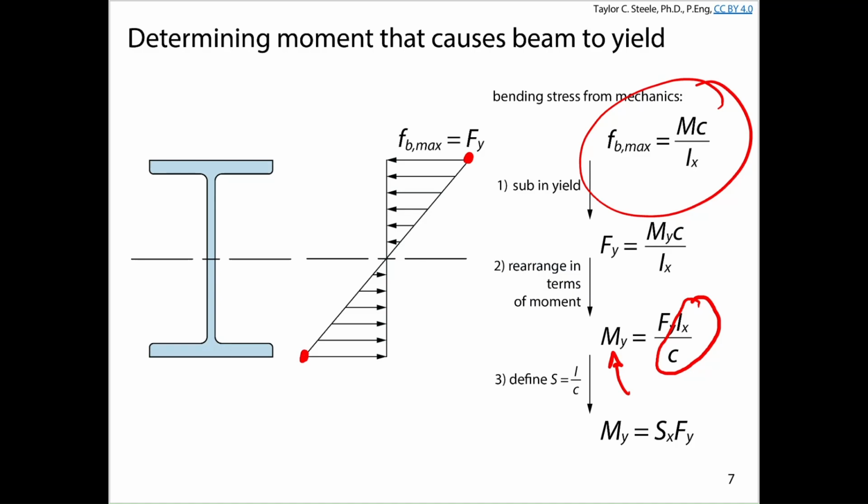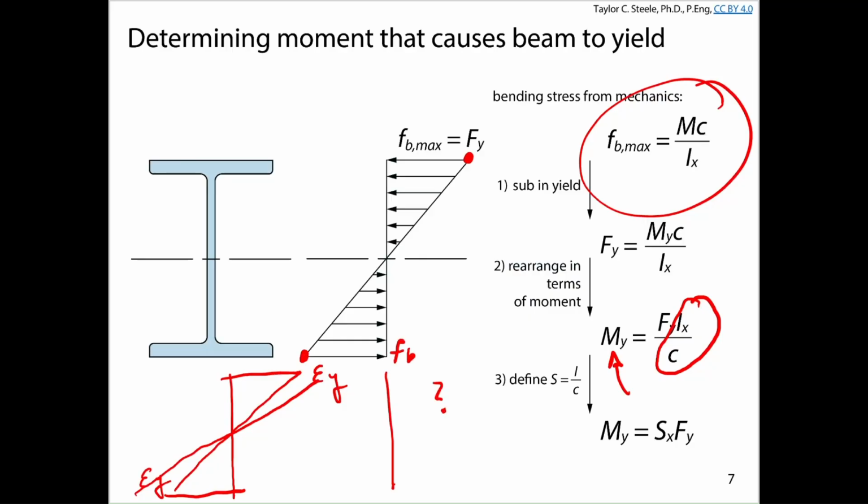So maybe you're saying, okay, well, Fy is just the yield strength. I mean, we don't want to damage the beam, maybe under service loads, but if we want to prevent collapse, maybe we can continue stretching the stress beyond Fy. Right? So maybe we could say, well, let's plot the strain diagram, and let's just say, this is the strain, and this is the strain at yield. Maybe we can exceed that strain, right? Maybe we can say, okay, let's try and go a little bit further. The question is, if we go a little bit further, what does the stress diagram look like, right?